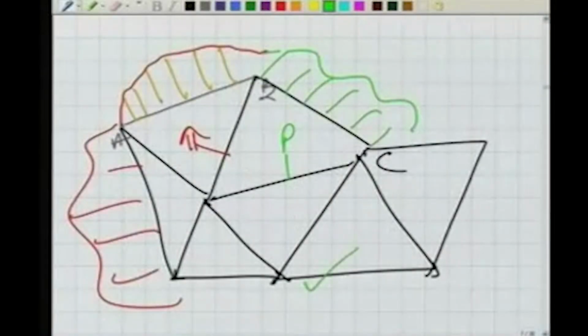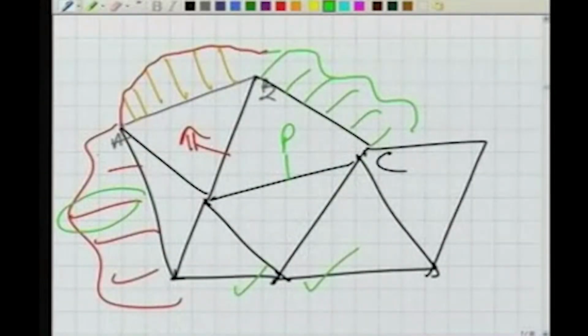Later on, we can start plotting the offsets, the individual details. So this is really working from whole to part. First, we have fixed the skeleton, the entire area. Then we are plotting the individual details. So what happens in this case, if my skeleton of the area, this net of triangles, is correct, and I am committing a little mistake here, then my boundary will shift only like this.